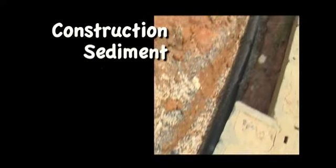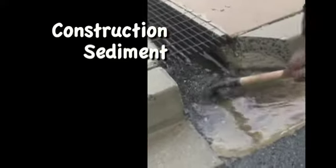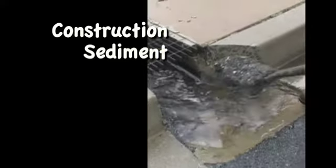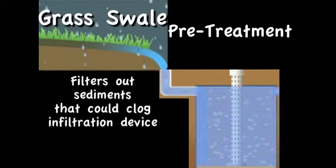Stormwater must flow into the infiltration device without carrying sediment or other things that may clog it. This may be achieved by pre-treating the area with grass swales or water quality catch basins. These devices reduce the amount of suspended solids and particles that will cause the infiltration device to fail over time.